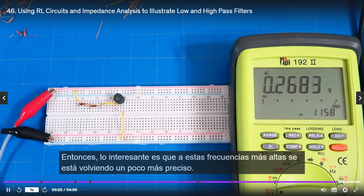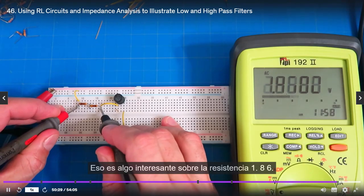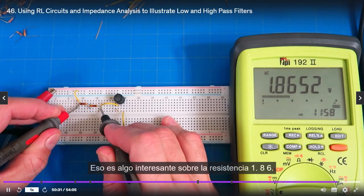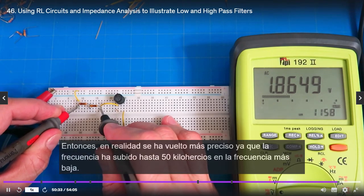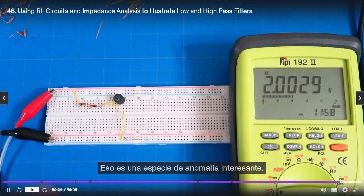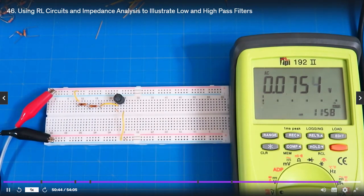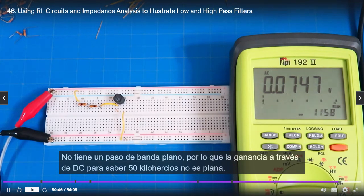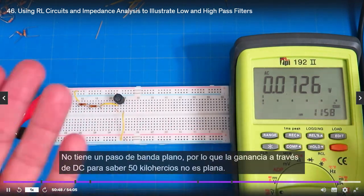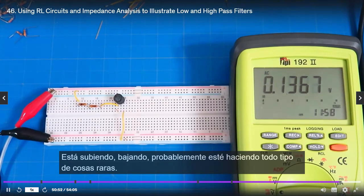So what's interesting is, at these higher frequencies, this is getting a little bit more accurate. So over the resistor, 1.86. So actually, it's become more accurate as the frequency has gone up to 50 kilohertz. At the lower frequency, it's not very accurate. So that's kind of an interesting anomaly. So this particular meter does not have a flat bandpass. So the gain from DC to 50 kilohertz is not flat. It's going up, it's going down, it's probably doing all kinds of weird things.